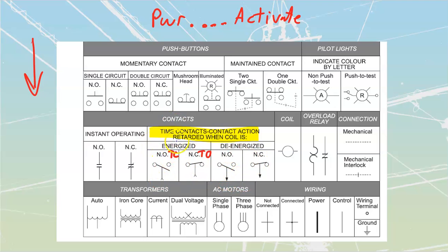This was what we refer to as the on delay category. This one is my off delay category. I'll draw them with a blue marker. The off delay are different in that when we power them up, they are going to instantly activate.